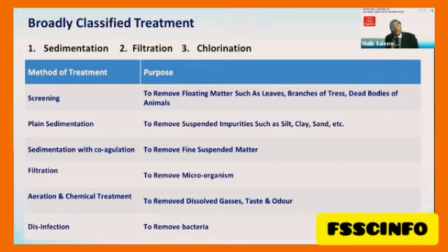And then in ultrafiltration, even for the microbes, you sometimes don't need chlorination if your storage capacity is not much higher. Otherwise, you can have drinking water without chlorination as well. When you do the chlorination of the water, then you have to do the dechlorination through activated carbon filters or sodium metabisulfite or calcium metabisulfite. This is a process which we need to understand.